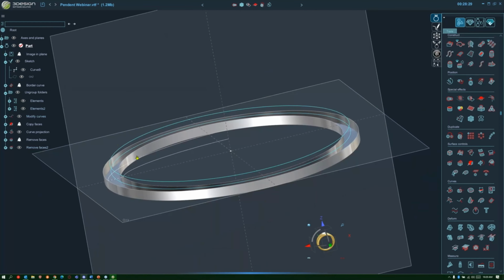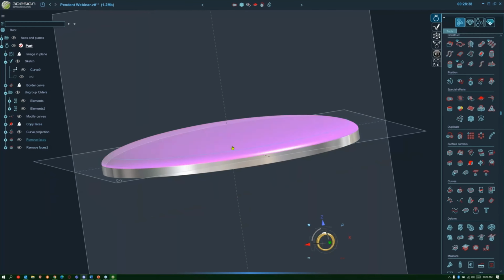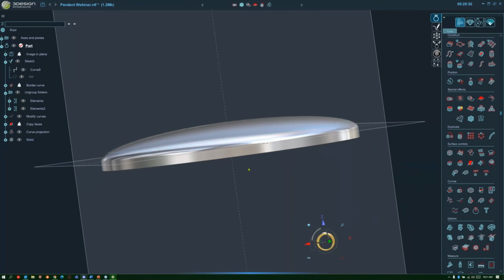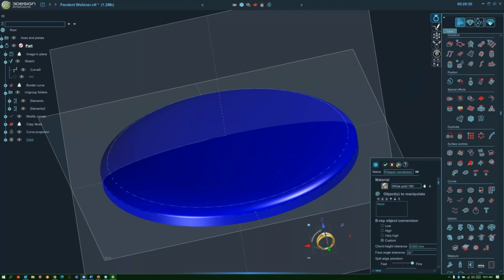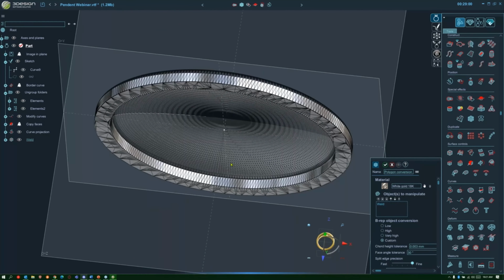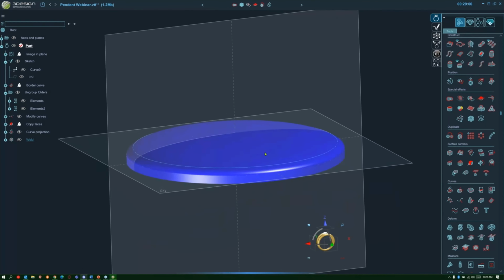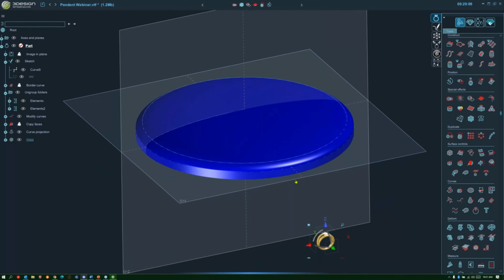So you can see now it's going to be two halves all hollow, but they do match up at the seams. So we can now weld these together. Remember, Booleans for solids, welds for surfaces. So go into surface controls, take those two surfaces that match up and weld, and all you have to do is validate that. And now we have a nice solid. And we can do a polygon conversion check real quick to see that it should be nice and clean. So we should have no problems cutting away from that and adding to it. Cancel that polygon conversion. Okay.